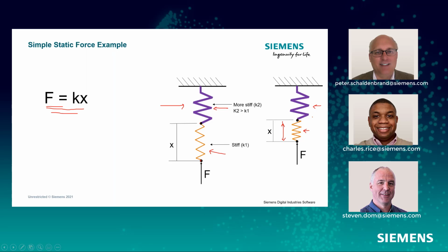That's a pretty complex model. To get those forces, you could try and do simple measurements like displacement across the mount. But the reality is the mount is not the sole stiffness in the system, in a dynamic system, right? You're up against something that has some springiness to it. And so when this compresses, our estimate for the force could be a little bit off, right? Yep. Especially the closer these are to each other, the more off it is.